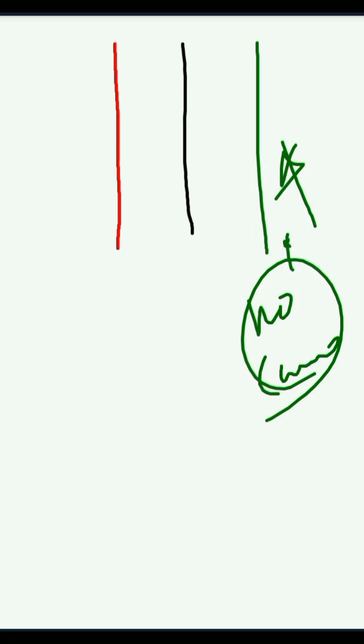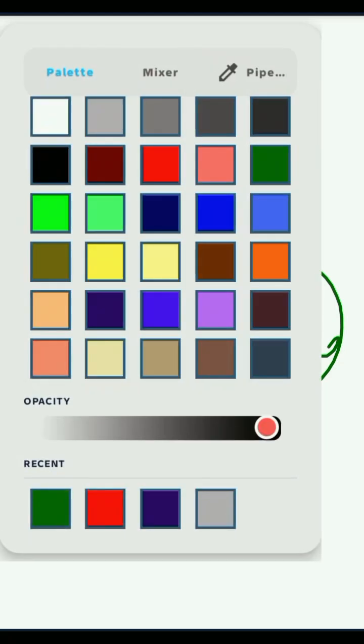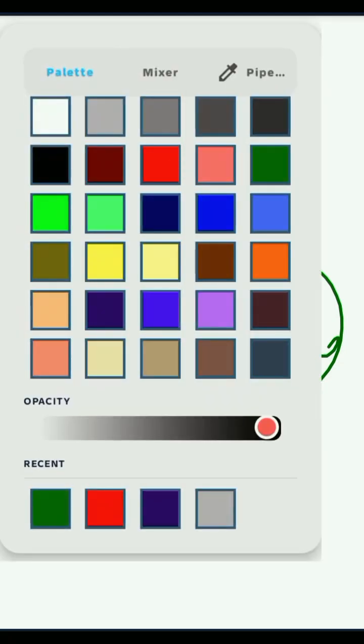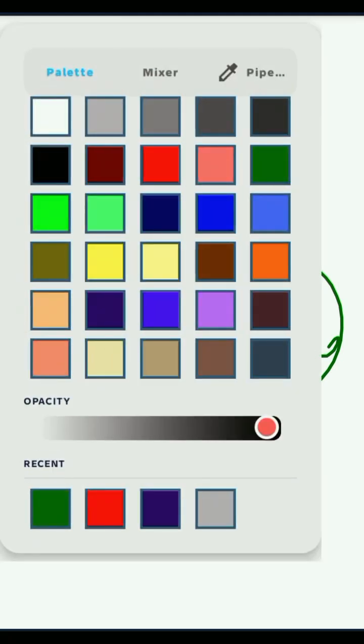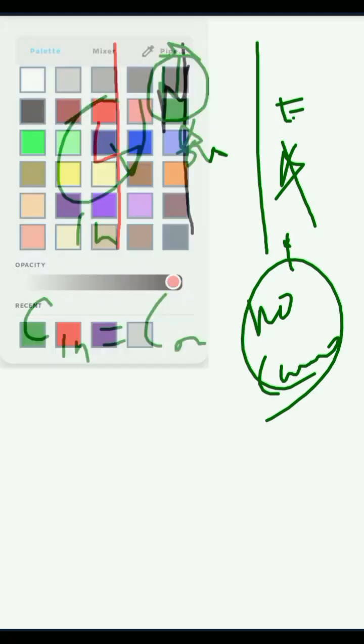And again, we expect that the total current in should be equal to current out. So this is in, this is out, back, this is the neutral. Then we have the live, and then we have the earth. So we're expecting all the current coming in through the live to be exactly the amount of current going out